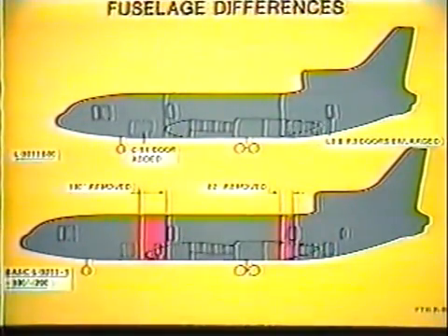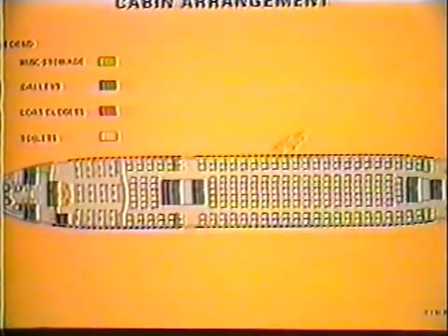The basic fuselage differences of the -500 from the basic -1, -100, -200 aircraft are: the fuselage is shorter. The -500 has only 3 sets of entry doors. The underfloor galley is removed, and the forward cargo door is much larger. Since there is no underfloor galley, 3 galley complexes are located in the passenger cabin.